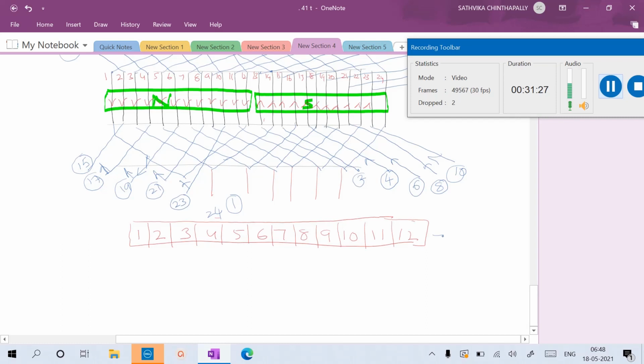Now you connect the front connections to the commutator segments. In this case we started from conductor 1. You can see this is conductor 1, and this conductor 1 is connected here and closed with conductor 12 here. Then let us connect this commutator segment to 3. Next, the third conductor is connected to the nearby one.